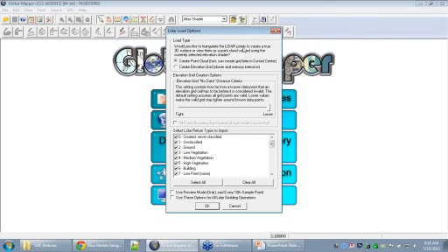And when we load in LiDAR to handle that data, at the very top, it's going to ask us how we want to load it. If we want to work with a point cloud, which is going to load that in as essentially a vector layer of discrete points, or we can automatically create an elevation grid, which takes a little bit of analysis.